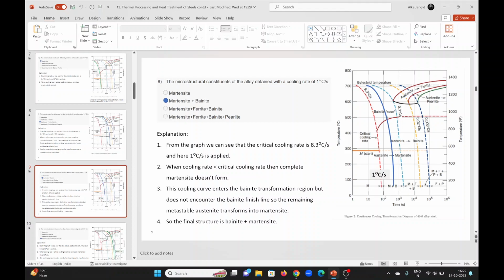In case when you are drawing your iron carbon diagram or these diagrams that you are plotting, you are considering pressure to be 1 atmosphere. So in that case, you can only vary temperature. So you are taking plus 1 in that case. You are taking plus 2 in case of water, where on one axis you are taking pressure, on one axis you are taking temperature, so you can vary both of those.